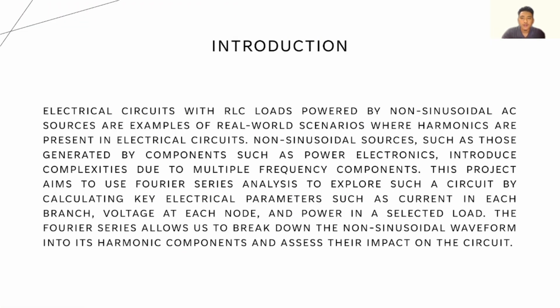As an introduction, electrical circuits with RLC loads powered by a non-sinusoidal AC source are examples of real-world scenarios where harmonics are introduced into electrical circuits. Non-sinusoidal sources, such as those generated by power electronics components, introduce complexities to the circuits due to their multiple frequency components.